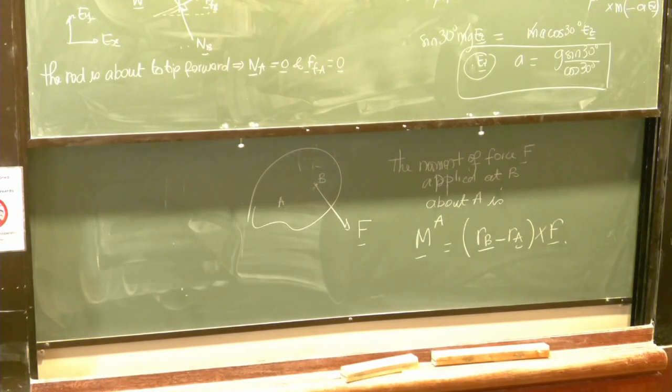How is it going? Are we finished? Close. So we have the two moments acting about it. It's going to be MB and F. Yeah, the moment of the normal force and the friction force at B, exactly, because the weight is cancelled out, well, 0. Yes. So we're missing one more now. Sum of moments about C is H dot C, which is 0. Sum of moments about C is the moments of the two forces at B. Their moment sum about B should be equal to 0. Equations are still the same.